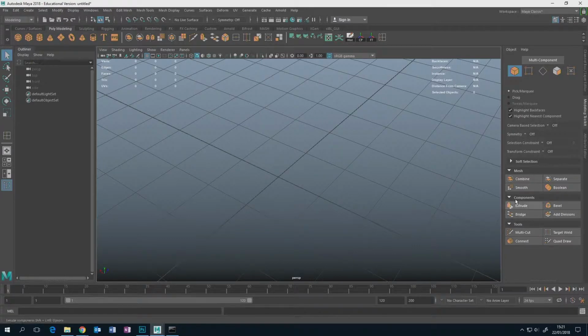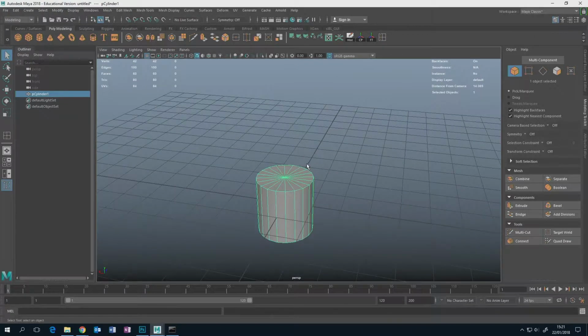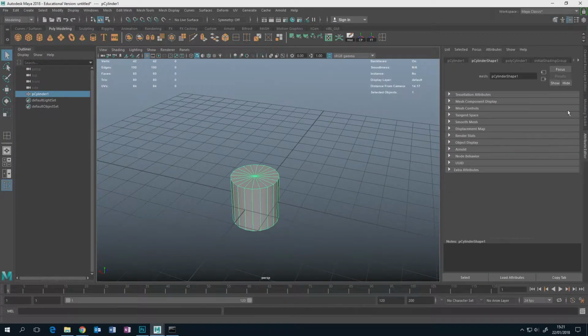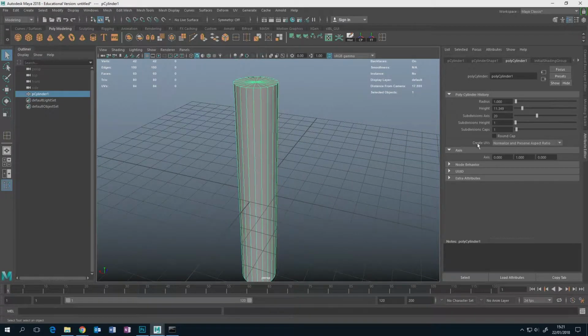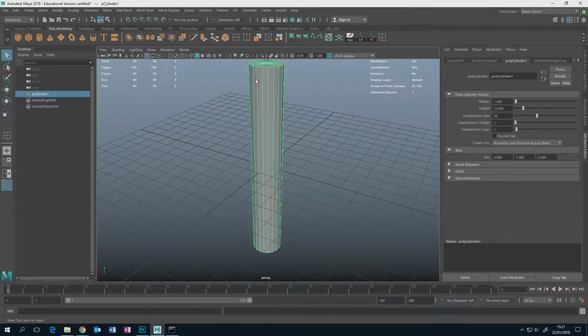I'm going to show you a couple of buttons I like to create to speed stuff up. One of the things is putting the pivot point of an object onto either a certain vertex or in the middle or the center of a bunch of vertices or edges or anything like that. Normally you'd have to do it like this. You'd have to go vertices, select them like that, and then go modify center pivot. So now when I go to object mode, that's where the pivot point now is, like this.